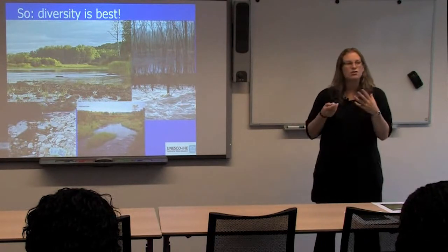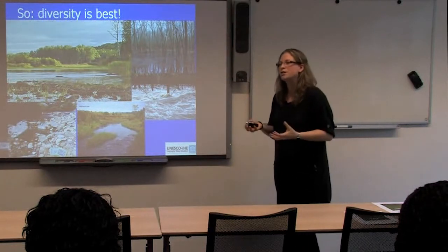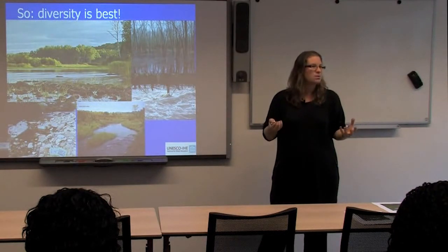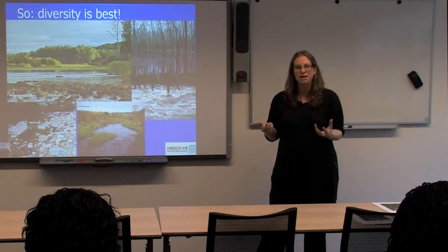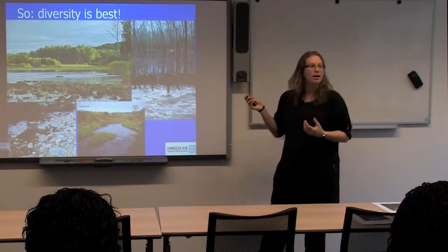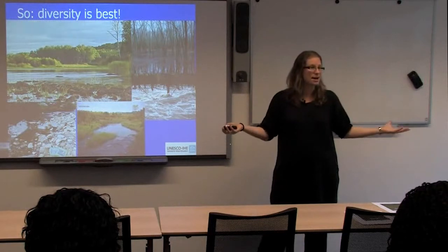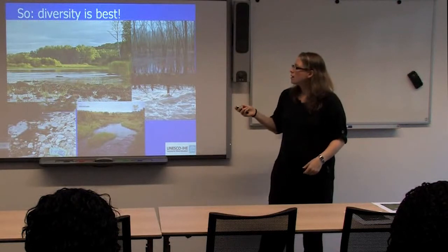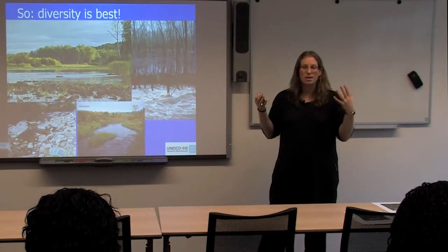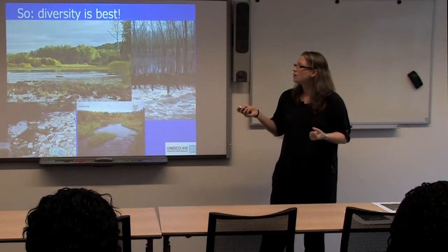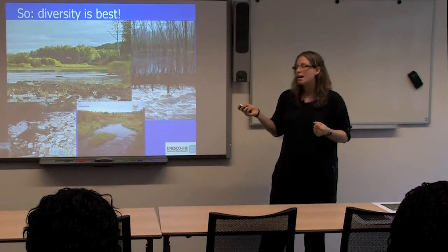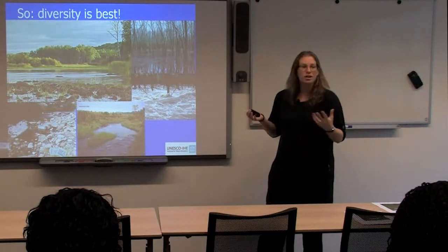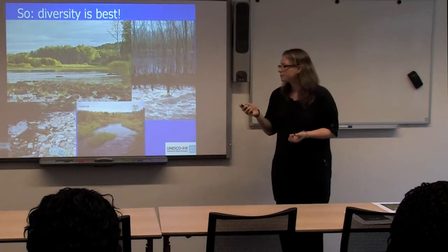But what is important is recognising the components of the ecology that require the water. What do you want in ecological terms, and what does that need? What does that mean for the hydraulics? Do you want riparian forest, which requires you to inundate it every year? So do you need to get the water onto the floodplain every year? Or are you looking to make sure that particular fish are safe, in which case you need to talk to the fish biologist about what kind of conditions that particular species needs. And then you need to go out and recognise that on the river.